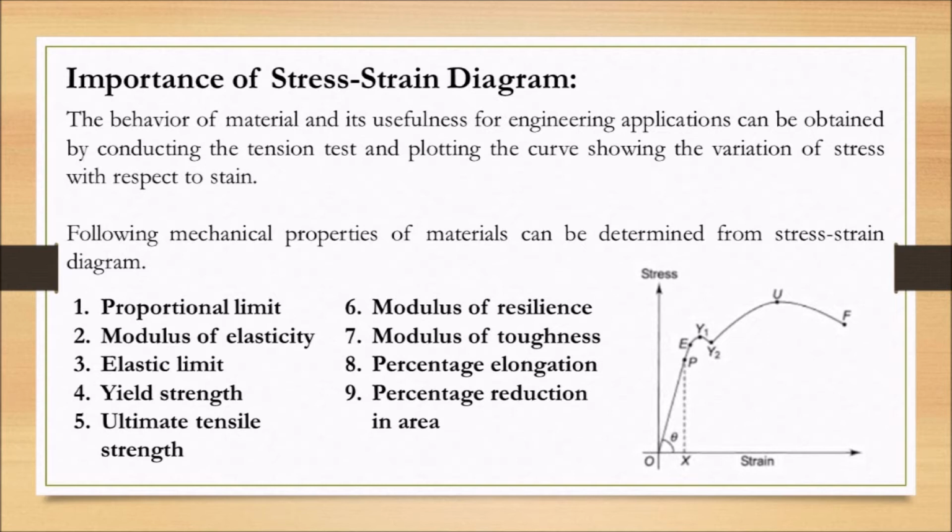To get the stress strain curve for a specific material, there is something called the specimen tension test, for which a specimen meeting the ISO standard is required. Along with that, specimen tension test equipment is also required. With the specimen and test setup, a tensile test will be carried out, and with the test readings, a stress strain plot will be drawn, and this is called the stress strain curve. A sample stress strain curve is shown here.